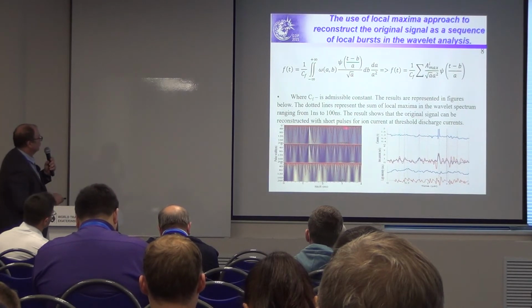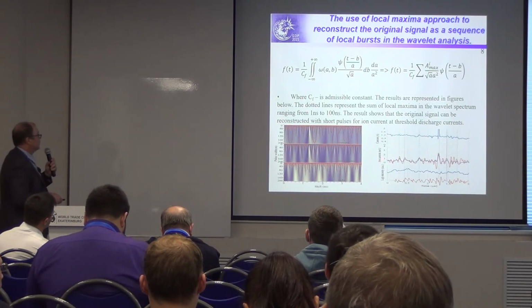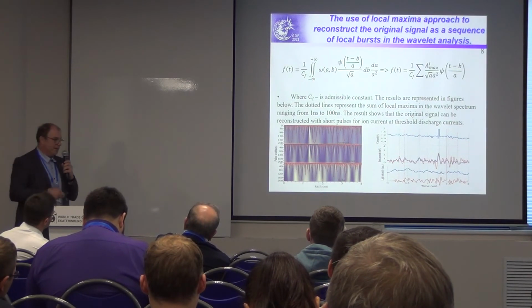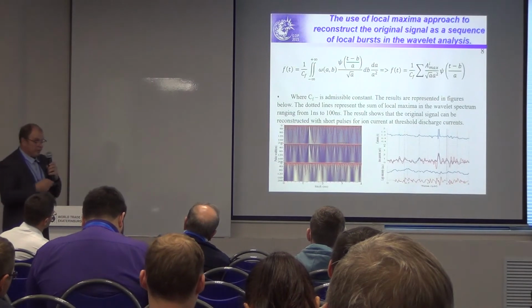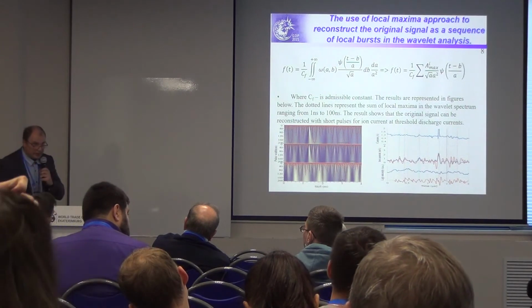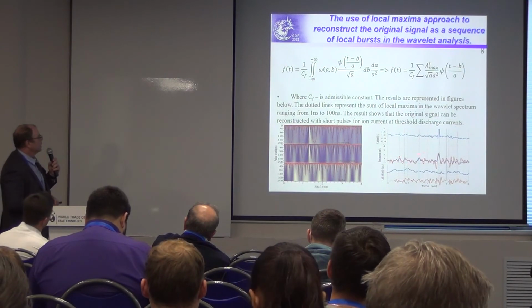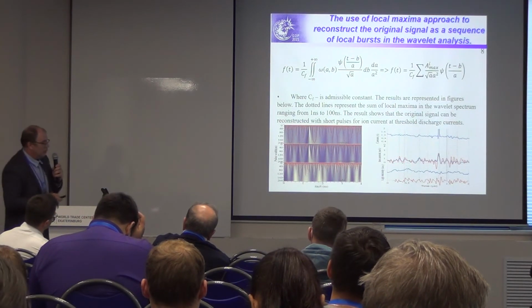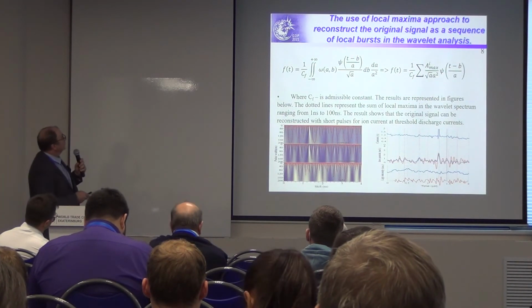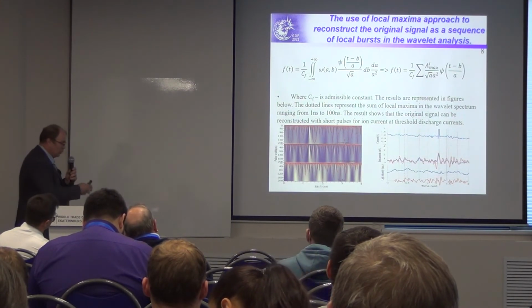We substitute the whole spectrum by these maxima, so we can restore the initial waveform by the set of pulses of wavelet analysis. The wavelet was made with the use of the Mexican hat wavelet. And we can restore the positioning and duration of pulses. So we can quantitatively analyze the ion bursts from the cathode spot.